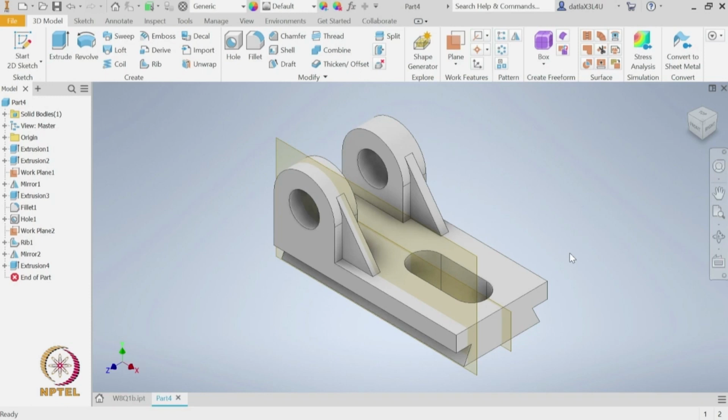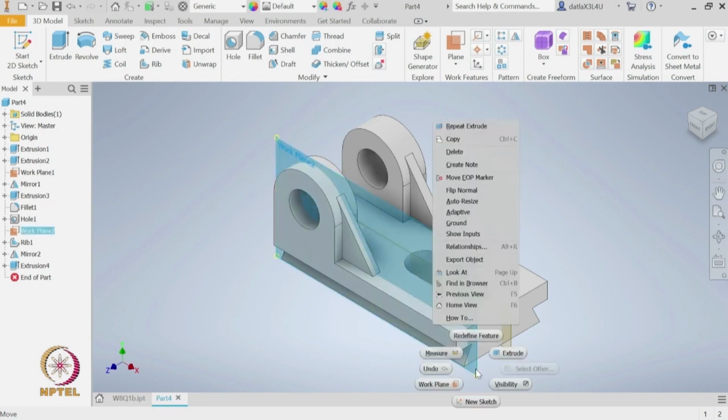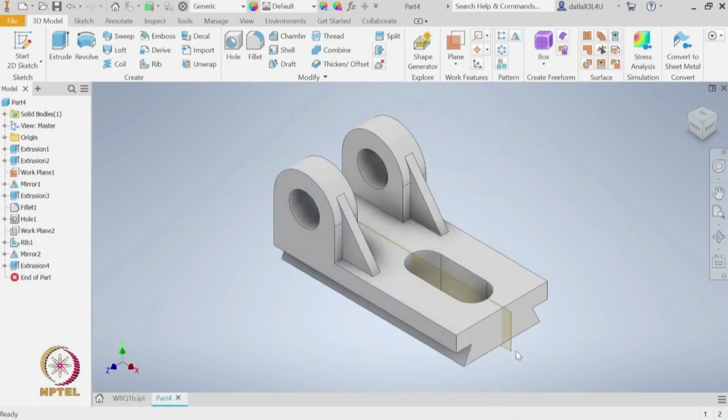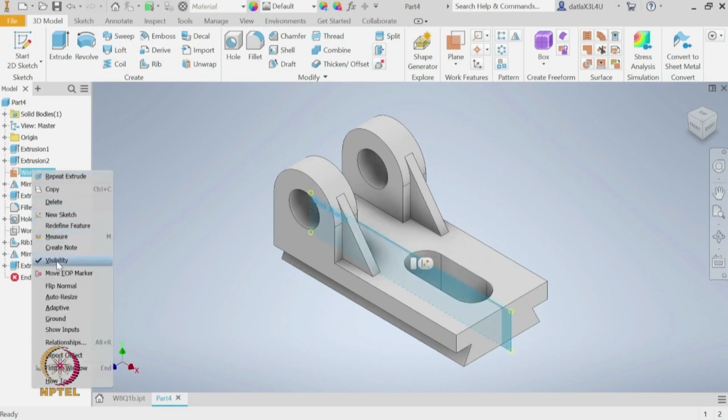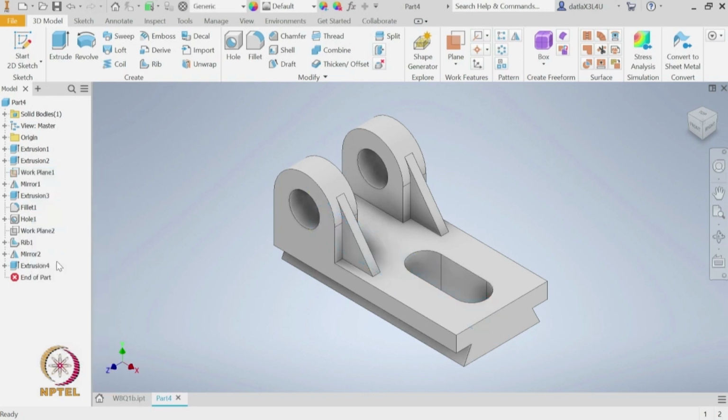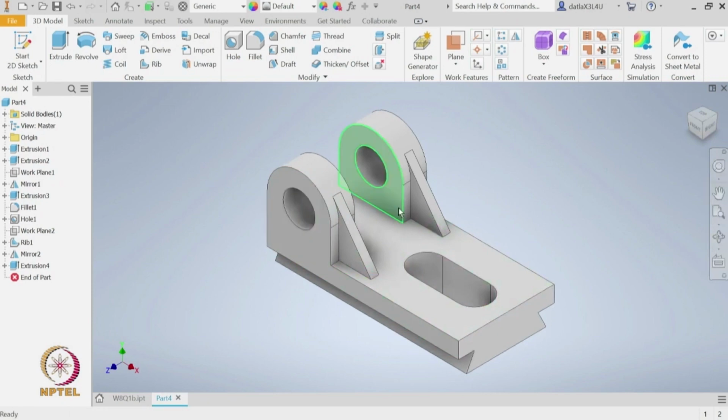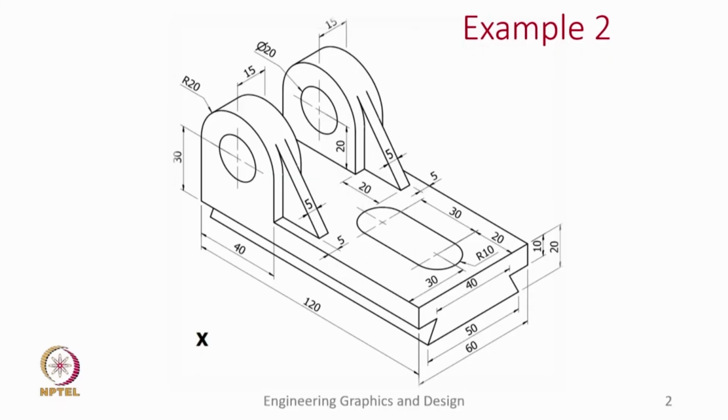final object, but if you think that these profile planes are not letting you see the complete final object, you can always disable the visibility. So, if visibility is now on, we will make it off. Similarly, you can do the same thing by first selecting this plane, right click and then visibility, we will uncheck it. So, now we see the final object that we started to work on.